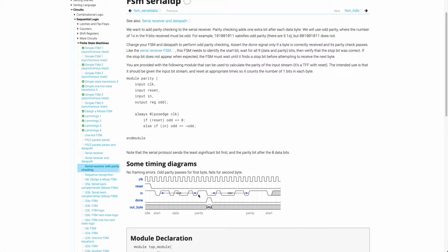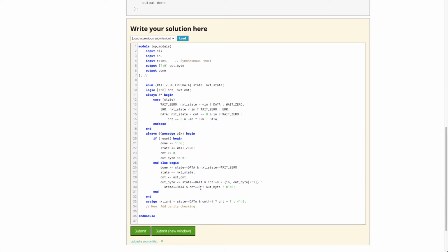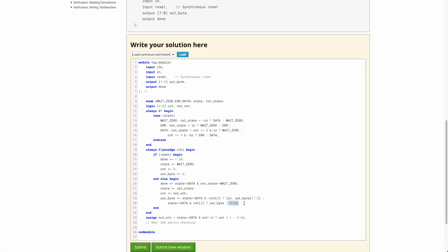I would just say, if not 8 or 9, then we would latch the data. So basically 8 is 1 0 0 0 if I'm not mistaken, 1 2 4 8. So if MSB is asserted, I stop shifting in data. Otherwise I keep the data. So I hold the data here and here, and then I release the data